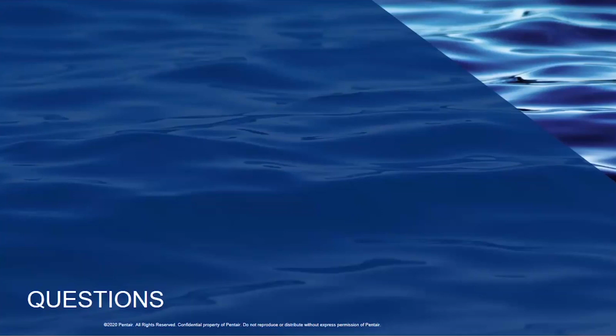So that's where progressive flow systems come into play. You're either going to cram too much water through a tank or not enough. If you have too much capacity to meet the flow, and you have only one, let's say manufacturing line, you don't want 6 tanks, right? Because with 6 tanks, that's too low a flow for all 6 of them. But it's fine for 1. But you start bringing on manufacturing lines, we're going to add 2 minutes of flow and then back it down. So yeah, variable flow situations add another layer of complexity here as well.